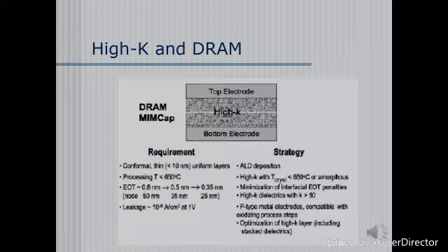For DRAMs, we need a way to minimize effective oxide thicknesses, or EOT values, and have a small leakage current. Metal insulator metal capacitors, or MIM caps, with metal of high work functions, are being researched. The main problem is that for these MIM caps to work, they must be compatible with the high aspect ratios that now exist in modern DRAM capacitors. By using atomic layer deposition, this problem may not linger in a few years.